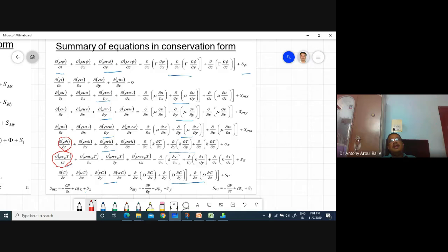Near the air conditioner you will have a velocity, then it will spread and the velocity will decrease, and again it will return back to the air conditioner. So there will be a flow distribution, and this flow distribution will be there much before the cooling of the room. That means the steady state of the flow is reached much before the steady state of energy. So we have different steady states.